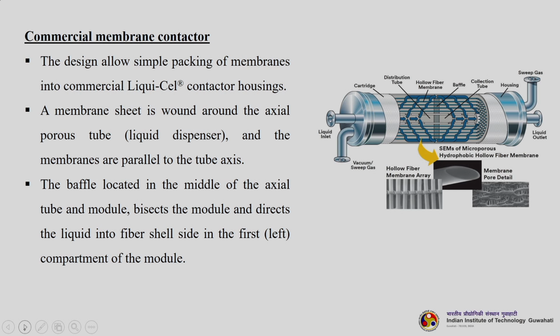So, the design allows simple packing of membranes into commercial Liquicell contactor housings. A membrane sheet is wound around the axial porous tube, and the membranes are parallel to the tube axis. Anyway, we have discussed these things during our membrane modules lectures, but I am quickly going through it so that you can recollect the things. The baffle located in the middle of the axial tube bisects the module and directs the liquid into the fiber cell in the first compartment of the module.